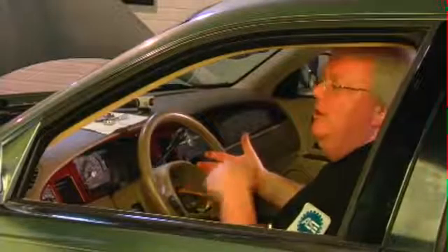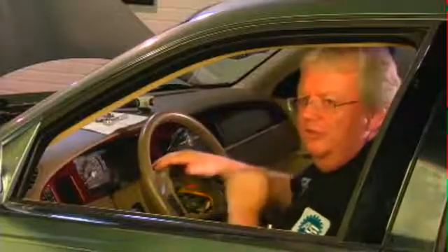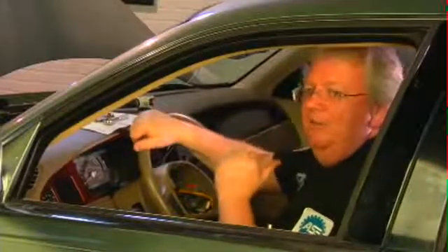But either way, they're going to have airbags in all cars today. Deactivate that airbag electrically and then unplug it and remove it like I just demonstrated. That may be a question you'll see on an A4 test also.